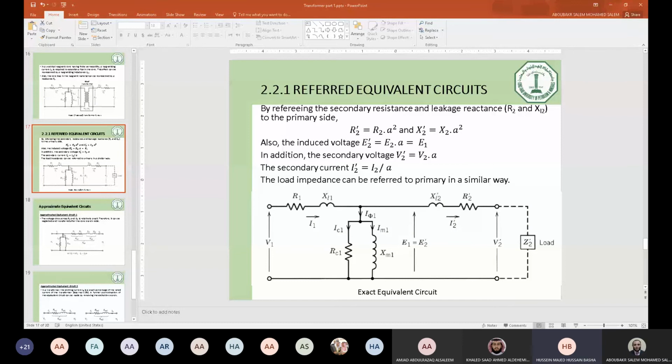Based on what I'm discussing now, the no load current for a transformer is maximum 5% of the full load current. This is due to the losses, or the amount of current needed to establish flux in the transformer is very small. So maximum 5%. This is number one.